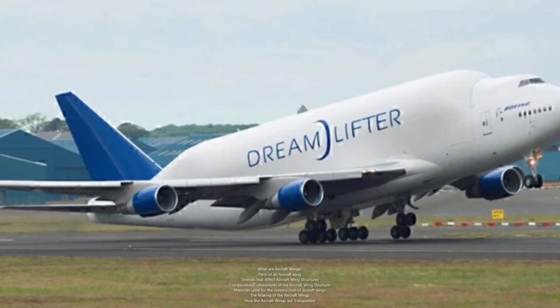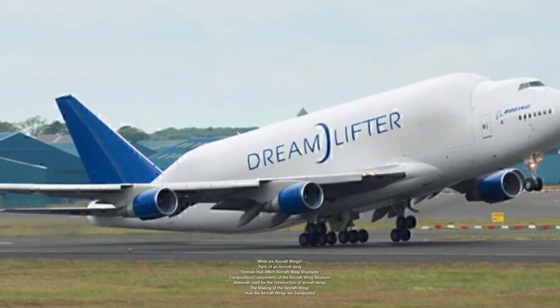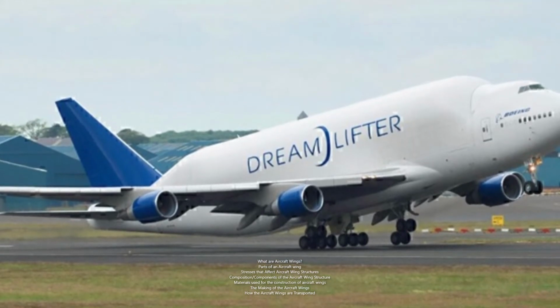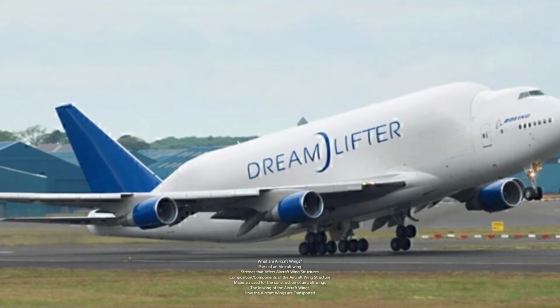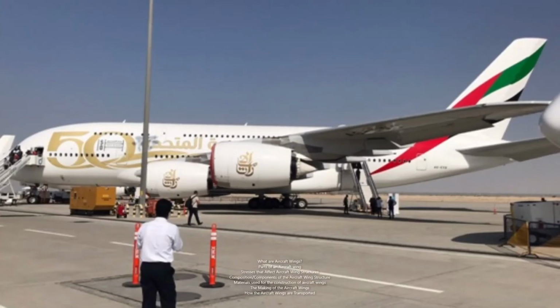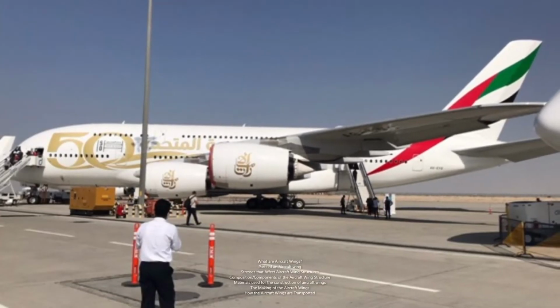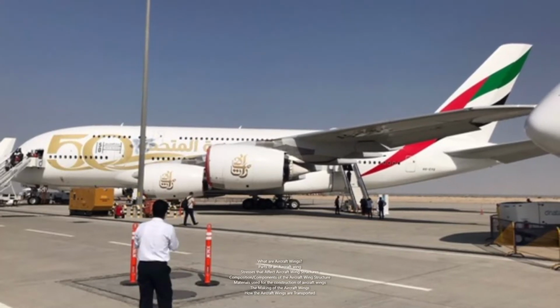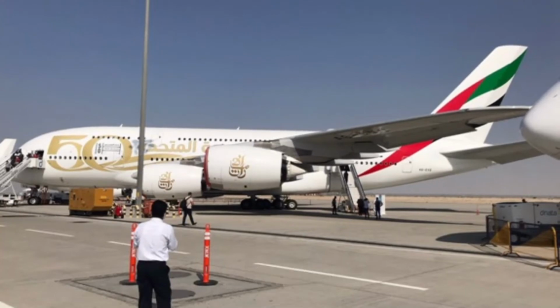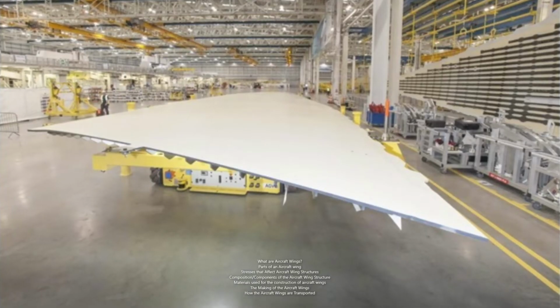When the lift is generated by the wing, it bends the wing upwards, creating a bending moment that has the corresponding compression in the top part of the skin and tension in the bottom part of the skin. Imagine pulling a piece of clothing upwards from both sides. The threads at the bottom part of the cloth will be stretched, tension, while the threads of the top part of the cloth will be made to squeeze inwards, compression. This is similar to what happens to the wing structure during bending.